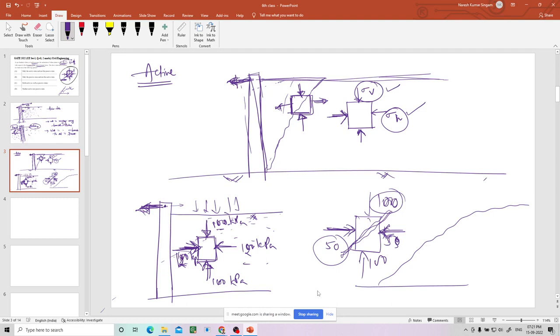See, and one more thing I discussed in the previous class, the collaboration between the Mohr circle and the earth pressures. I'll draw them now, okay. Now suppose this wall is moving in this direction. That means passive. It is in the passive condition now. At that time also, only sigma h will change, but instead of decreasing it will increase. Let us say 150. It has become 150. At that point again soil may fail, okay, due to changes in the stress.